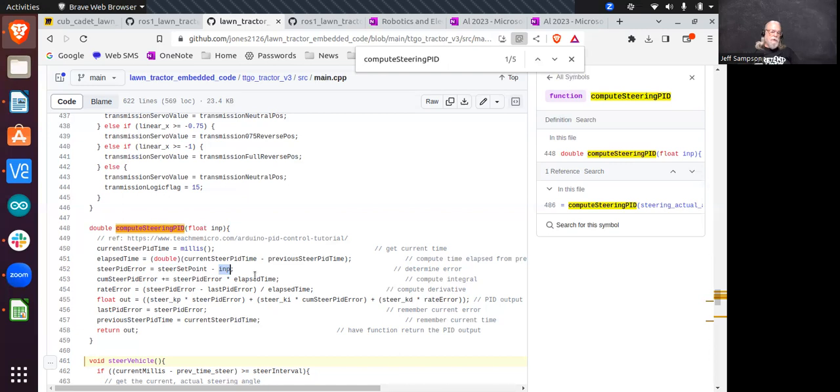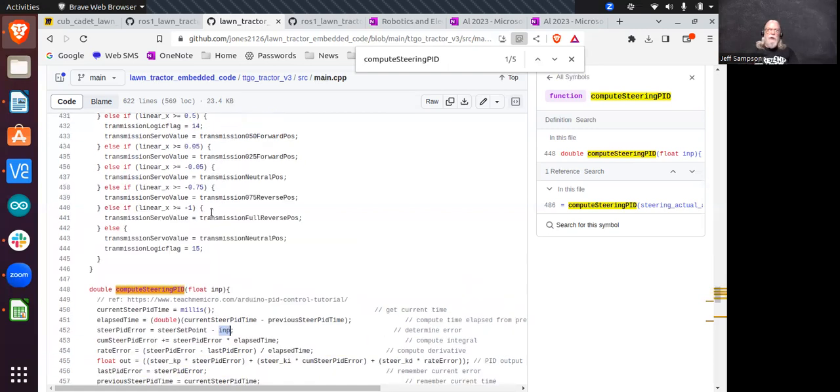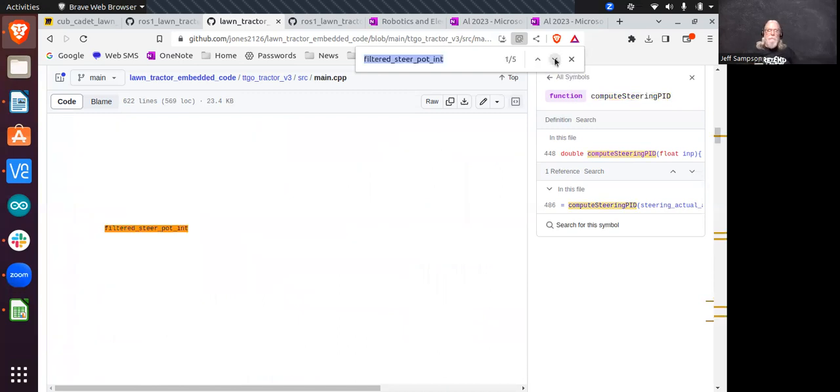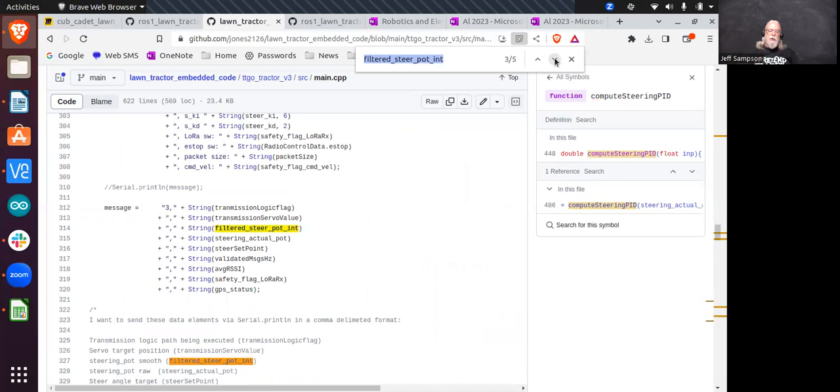And then also at one point I was trying to convince you that if you read the value from your pot and you're beyond a certain point, just kill power to the motor. So if it's trying to drive into the hard stop, say going left, if you read directly off the pot and we're at or beyond the point we gave it, then simply substitute the value you're supposed to be giving your PWM, just load a 0 in there, and that basically kills power to the motor. It still might bang into the hard stop, but the motor's going to be turned off when it's doing that. And it's going to do that less if you slow down the steering, like I was just talking about.